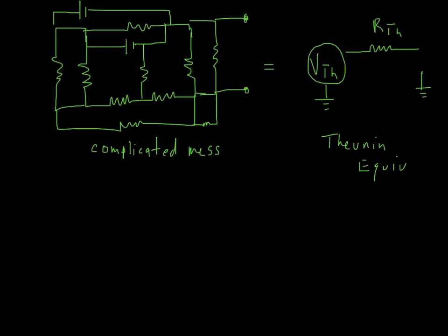What you would want to do is put on many different R loads onto this, and you'd measure the voltage drop across that load and the current through it. That was our chart before. So we had our graph, we're interested in V out and IL. So let's add a little load here.